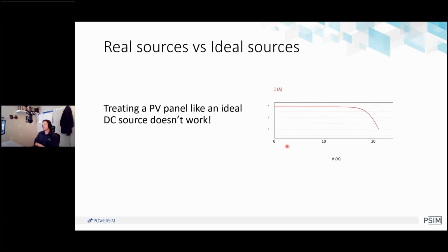I've seen issues where people series stack power supplies. So they'll have, for example, a PFC front end, and then another conversion stage, and they design the PFC. That works fine, and then they design their second stage with an ideal source, and they neglect the interaction between the two.